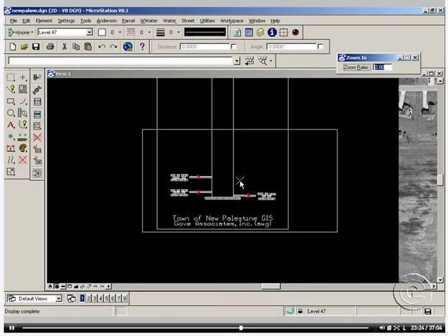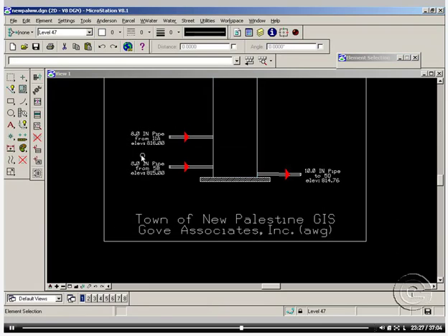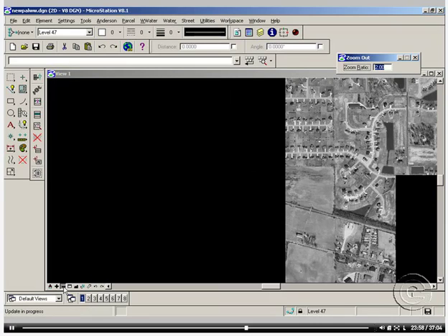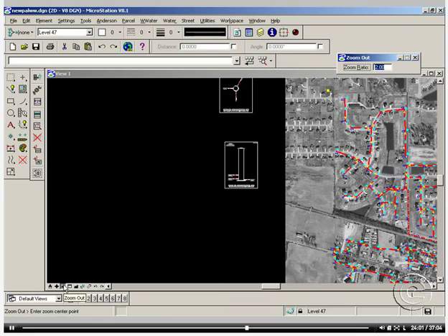And then as you zoom in, again you will see somewhat where the pipes are landing in and where the pipes are coming out of the manhole and going to a different manhole. And here again you would see that we have an 8-inch pipe from 11A, and it gives the invert elevation of that pipe. We have again an 8-inch pipe coming from 5B, again giving the invert elevation, and then we have a 10-inch pipe going to 5D, again showing the invert elevation. And this can also be designed in a way that it would show the logo, or some type of sheet that the company or the city wants to use.